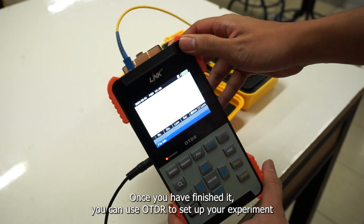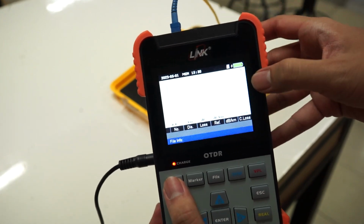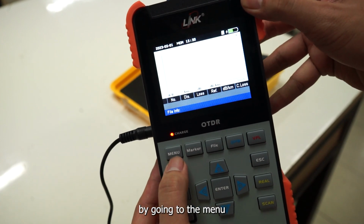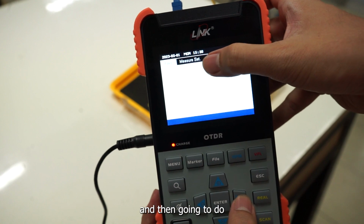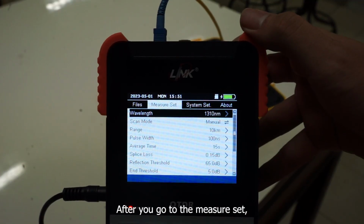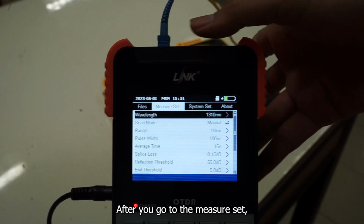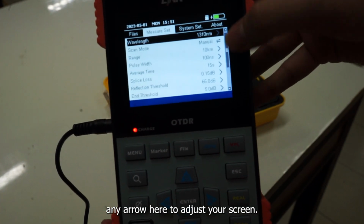Once you have finished, you can set up your experiment on the OTDR by going to the menu and then going to the measure set by pressing menu again. After that, you can press any arrow to adjust your screen.